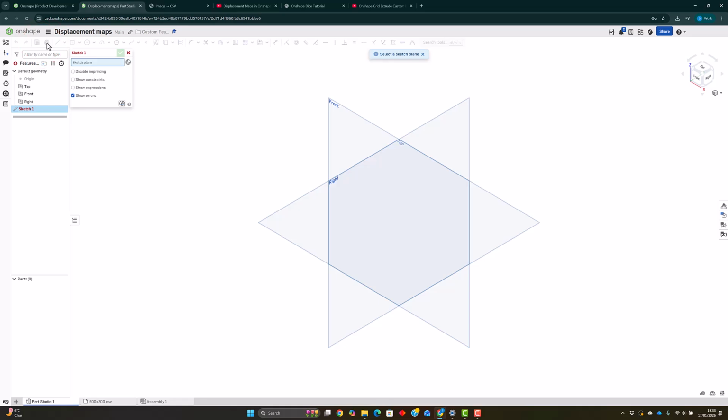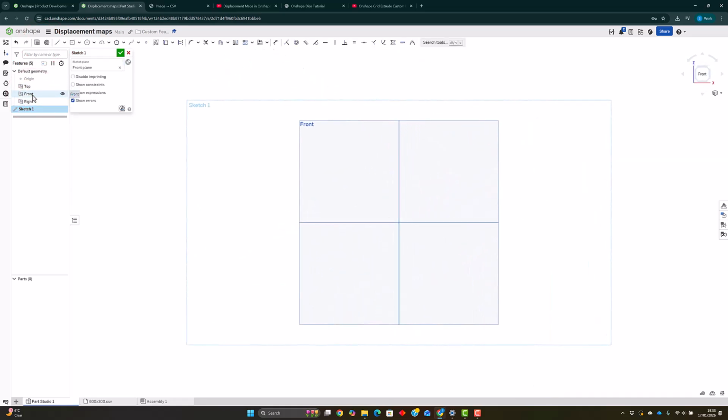So I'm going to click sketch, and I'm going to click the front and then press N. And I'm just going to draw a basic center rectangle, 100 by 150. So center point rectangle into the middle there. I don't think I've got my origin turned on. Let's turn on my origin. Click once, click again. Now remember, if you only click that second time to stop and you've got the box highlighted there, you can type your dimensions straight in. You don't need to go and use the dimension tool for both of them. And we've got our fully defined box.